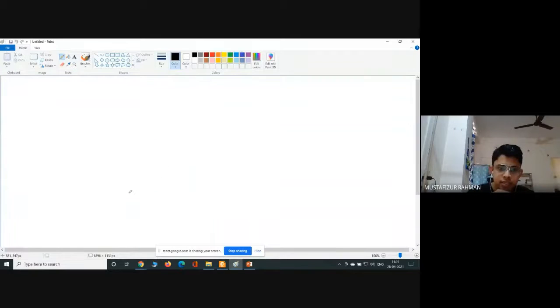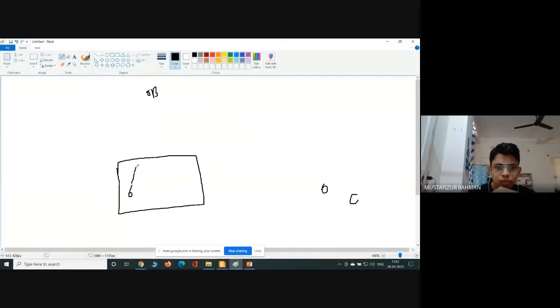So this is the method of intersection. We have point A here, point B here, point C here, say for example. Now initially what we will do, say for example, we are at point A. We have our plane table here. We will look towards the B point and we will draw the line, not according to scale, because we are not able to go there. That is why we are doing the method of intersection. Point A here, and in this direction somewhere we have point B. And then again we will look towards point C.